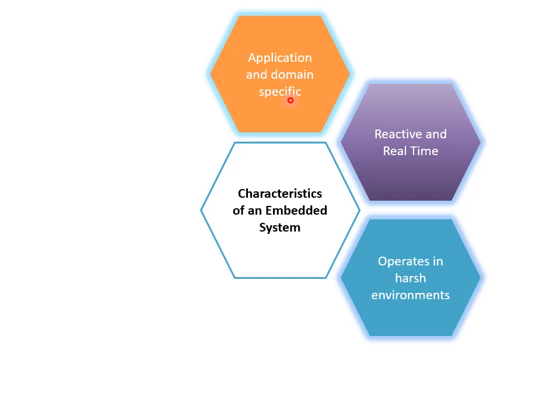So if my embedded system is deployed into such an environment, it should be able to withstand all these adverse operating conditions. The design should take care of the operating conditions of the area where the system is going to be implemented. If the system is being deployed in a high temperature zone, then whatever components you have used in developing this embedded system should be of high temperature grade, isn't it? It should be able to withstand that amount of temperature. Okay, it is going to be operated at 150 degrees Celsius, 200 degrees Celsius. My devices should be capable of withstanding that amount of temperature.